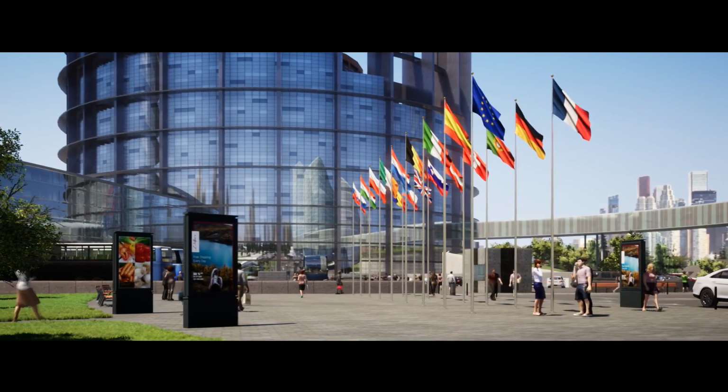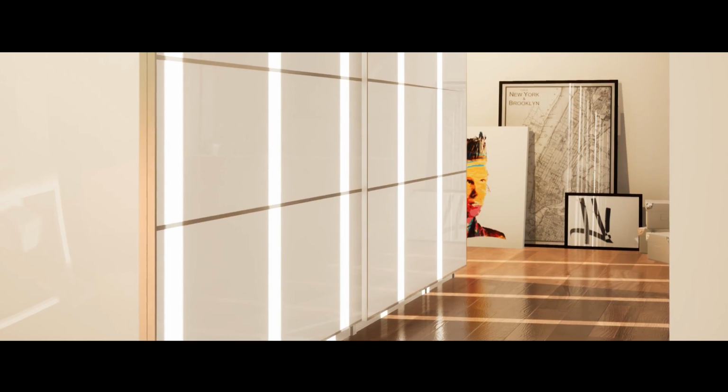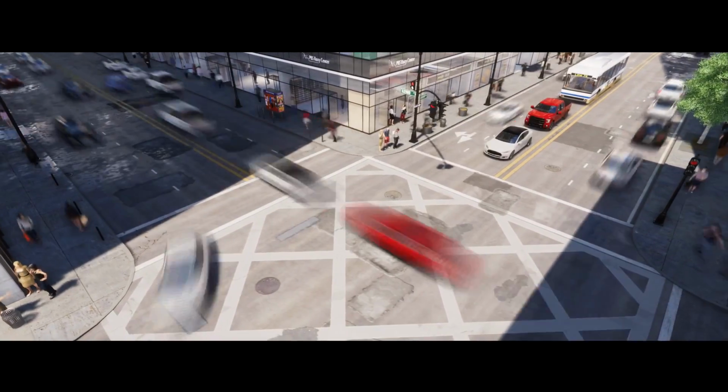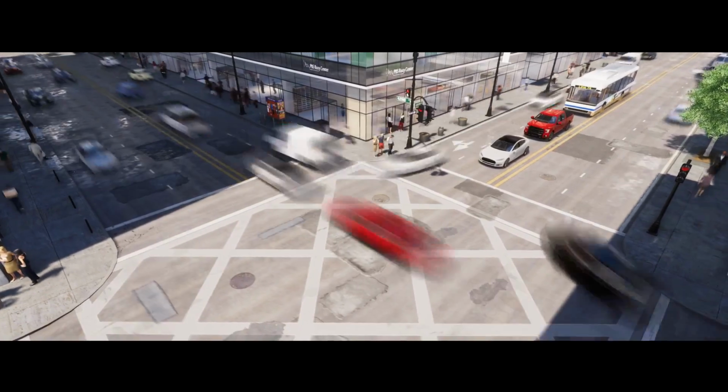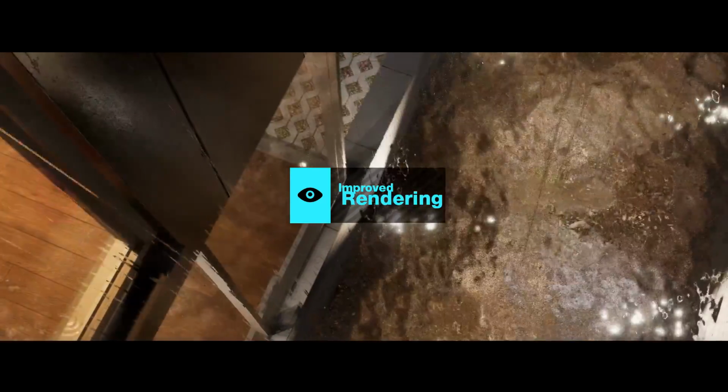Also, one thing that I didn't mention during this webinar is that at any time while you are working in Twinmotion, it's just one click to switch to VR. The shortcut is, let me remember the shortcut, it's F10. So if you have your VR headset plugged in, it's just one click to switch to VR.